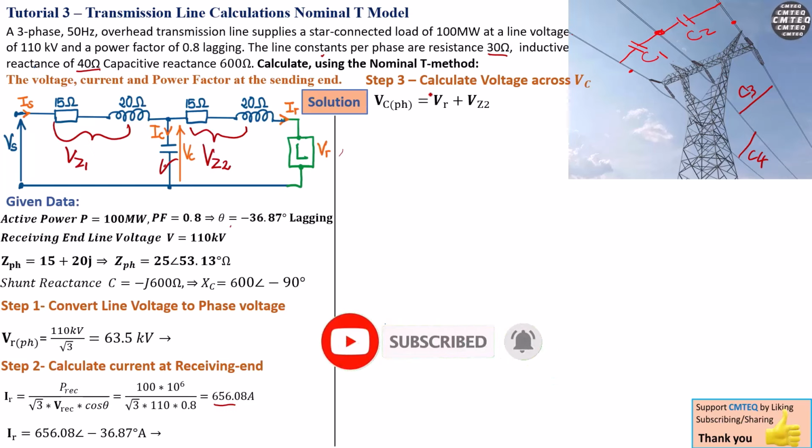Then that means V per phase is VR plus VZ2. That means VZ2 is actually IR times the series impedance, because the current flowing here is exactly the same current flowing there. Very simple, Ohm's law there.